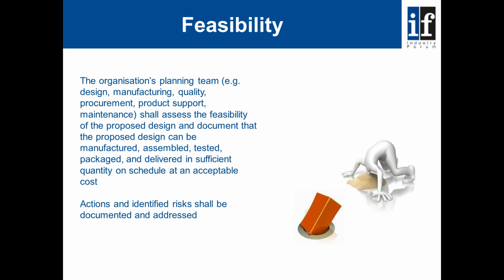And so feasibility is the real acid test of actually saying, okay, I understand the specifications, the tolerances, the requirements. They are within the normal area of the supply organization's expertise, and as a result they believe that the product that's being designed can actually be manufactured. So I guess feasibility is a good hold point. If any of the information that's required to make that decision is unavailable, then we really should not be moving to the next step until we've cleared that all away.